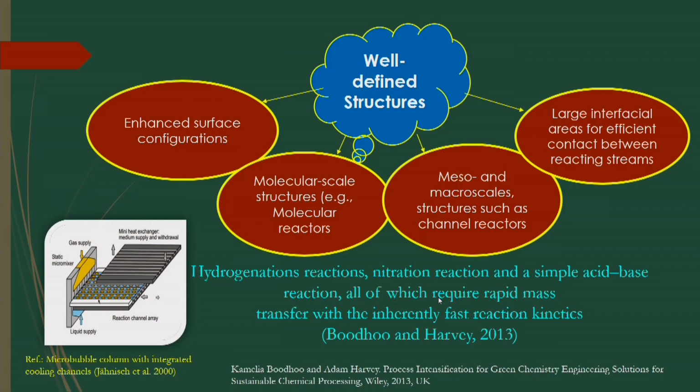Even sometimes channel reactors, the micro channels are being configured in such a way that you get more gas liquid mass transfer there. Even for heat transfer operations, micro channel based heat exchangers are being developed nowadays. There are even some micro bubble column reactors to get gas liquid reactions by generating micro bubbles. So, in that case the configuration of the reactors is also important for process intensification.